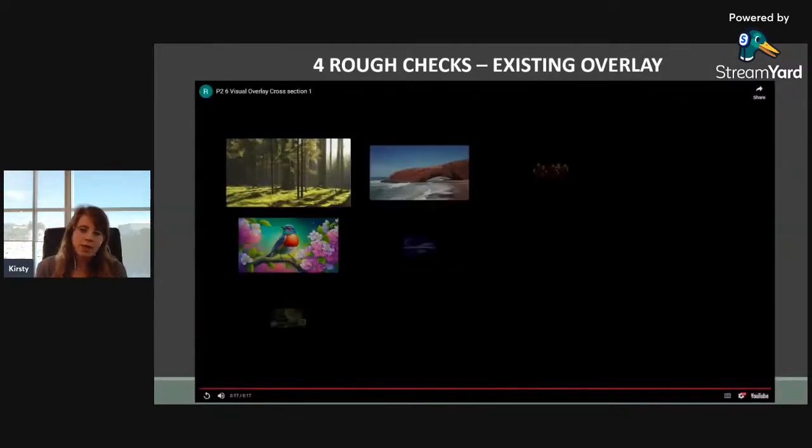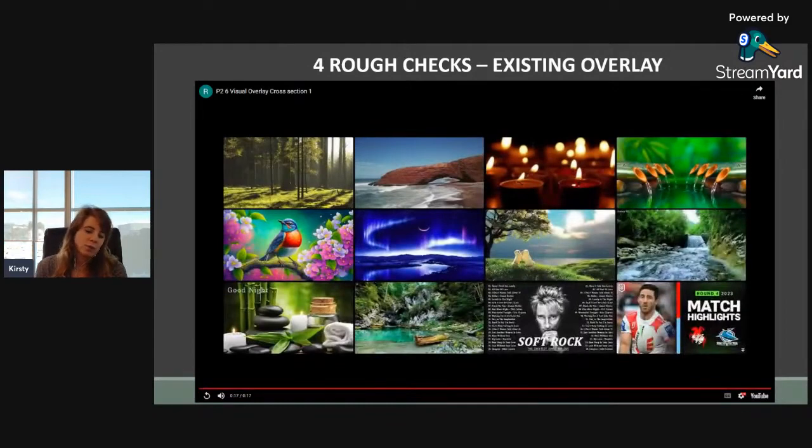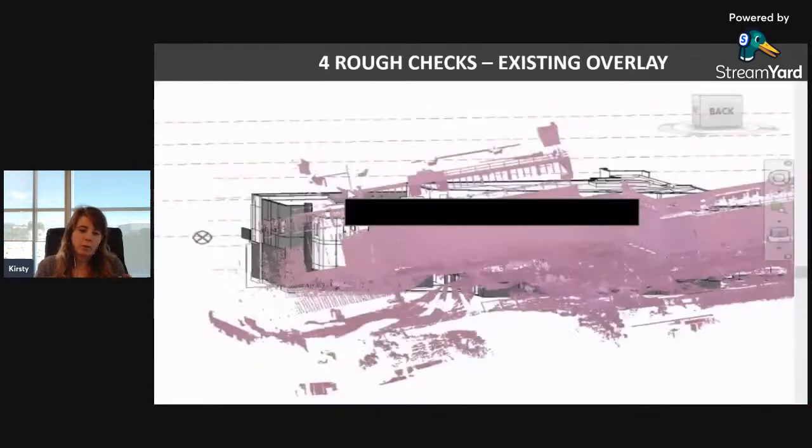So one thing to be aware of there is that it could be you've got not enough points along when creating those total station line work. But more often than not, it's quite good to just use it as a general rule to see. If it continues across the point cloud, then you know there's something wrong.